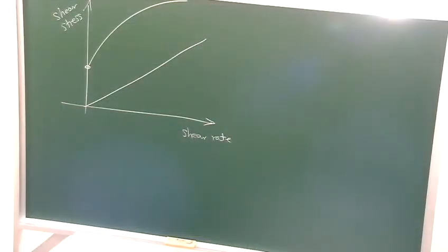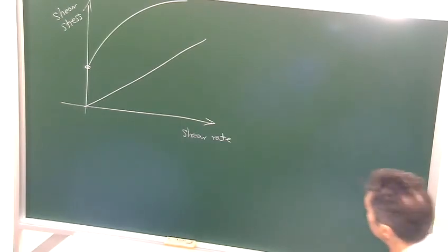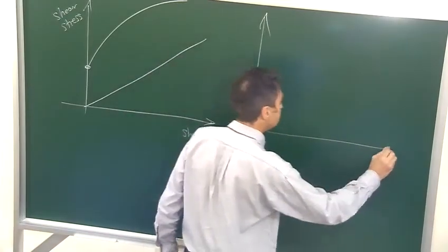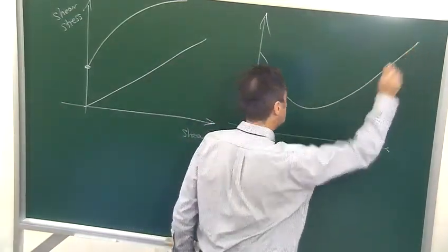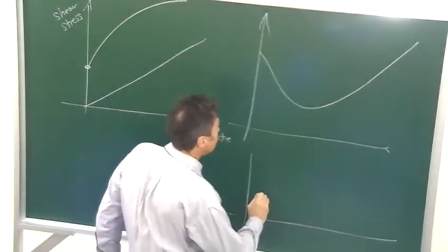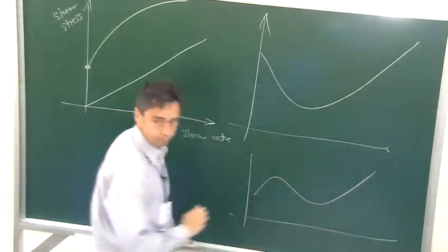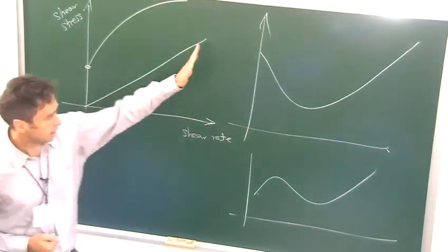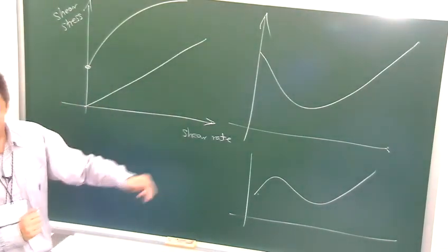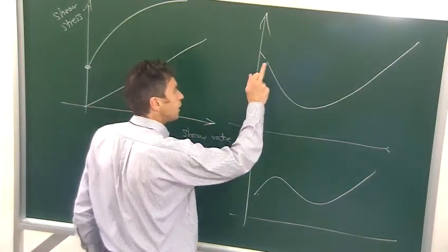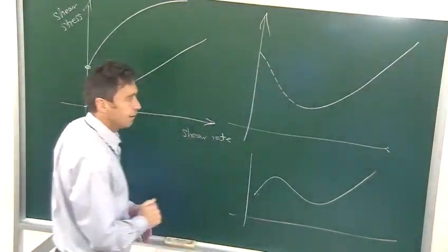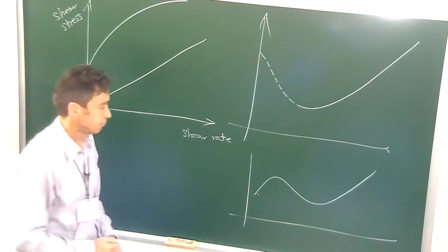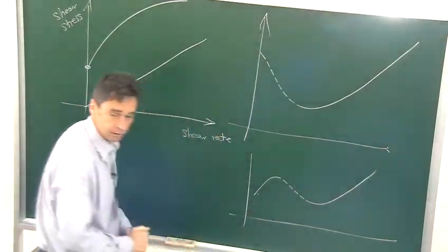And one of the things that people have observed, which is relevant here, is that this flow curve appears in some situations to do this, or to do this. So you've got stress against deformation rate, and the steady state flow curves that people interpret do something like this. And the interpretation is that if you have a negative slope here, it's like having negative viscosity, it's an unstable situation. So those are kind of unstable branches.